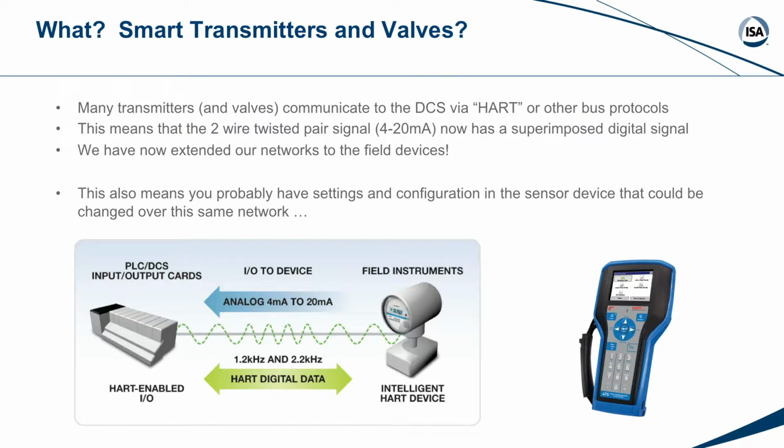But you essentially take that electrical signal that's been there for decades, that's measuring the temperature, communicating the temperature from the transmitter up to the system, and you superimpose a serial protocol on top of it. So now that transmitter can tell the control system things like what's its minimum span value or what's its maximum value. So what is the range?